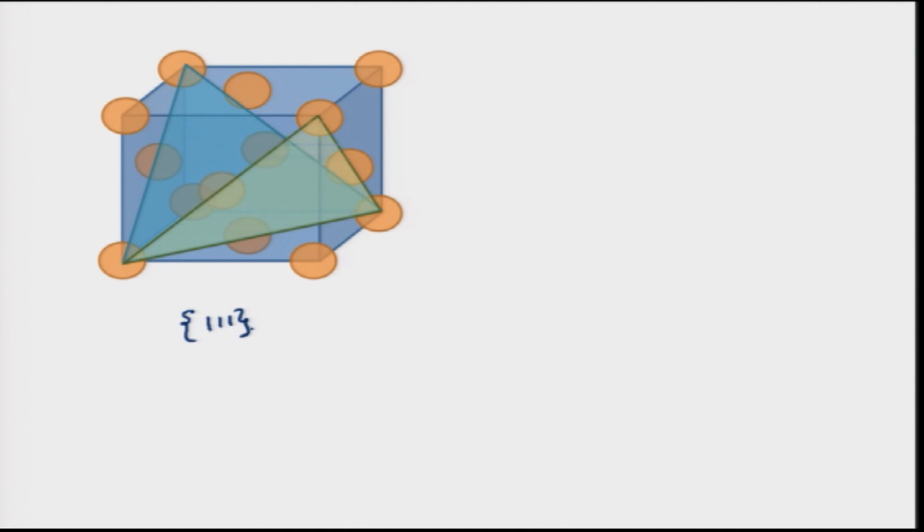Okay. So, now this is another 111 plane. This is connecting all the 110, this is another 110. So, this forms another family of 111 planes. Now, again you connect these and you get another family of 111 planes, and if you look closely, this and the line behind this also form another set of FCC planes.